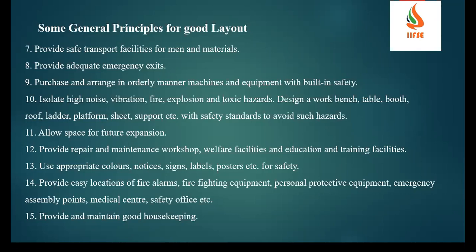For example, if a machine is running and you open the door, it will cut off the power supply. There are conditions such that if any guard is opened, the machine will stop. Also, in some cases, if the earthing is not properly connected, especially for critical equipment used in the oil and gas sectors, the pumps or motors will not start. It is the inbuilt feature of an equipment or machine to safeguard the people as well as property.